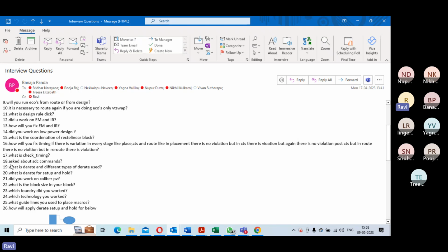If two cells are sitting very close next to each other, would the IR drop vary so much that they have different derates? Very unlikely. Because IR drop and chemical mechanical polishing vary with distance, but very close by, the variation should be minimal. That's the logic.